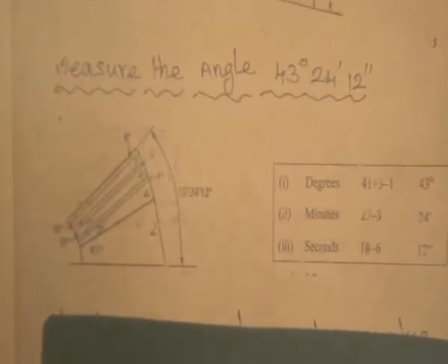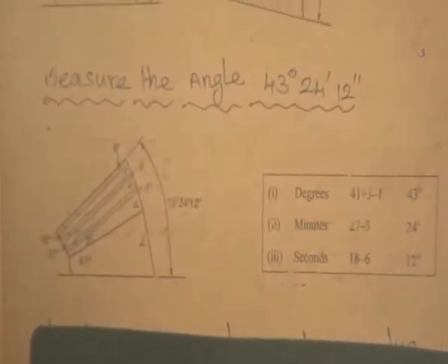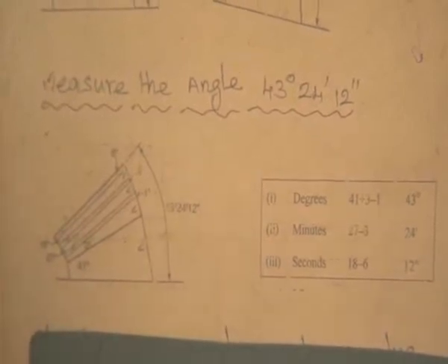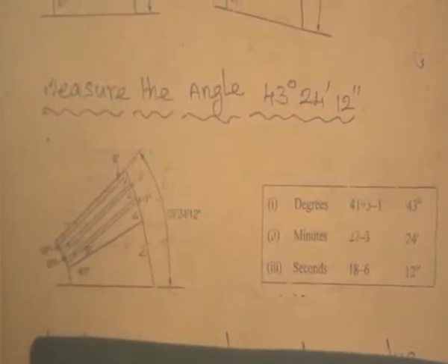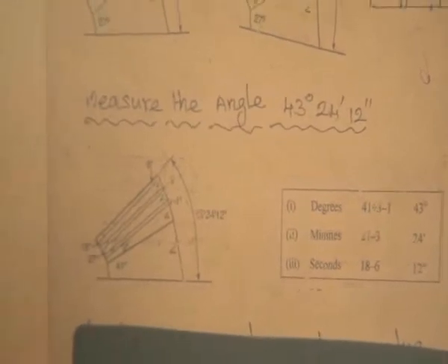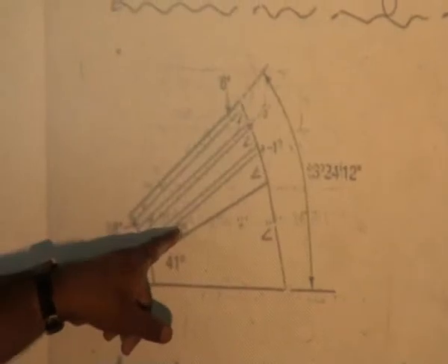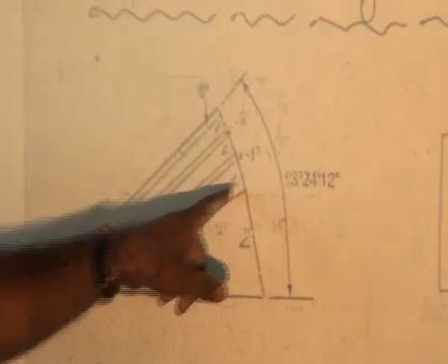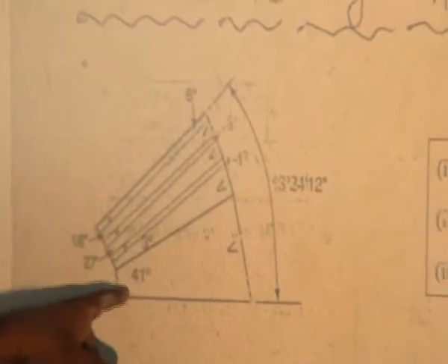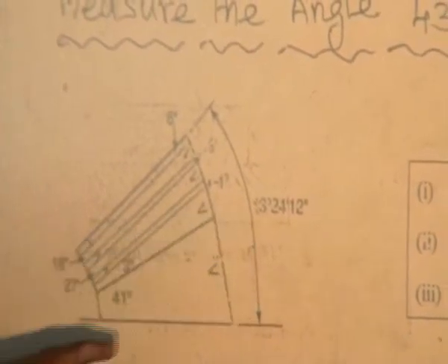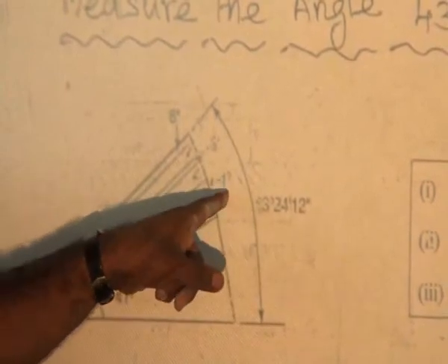And then, see the table. The next one available is 3 degree, that is 3 degree on the same symbol side. And then another 1 degree is available, minus 1. So we have to insert that component in the opposite direction. See, 41 degree is in the same direction, and the 3 degree symbol is in the same direction. Now the value is 44 degree, but our requirement is 43 degree.